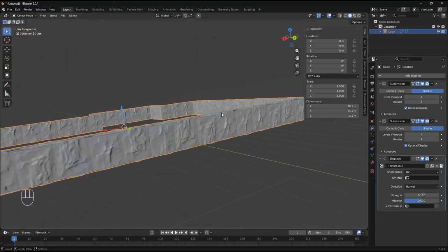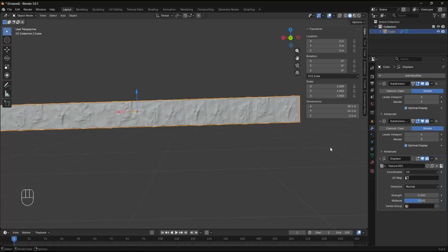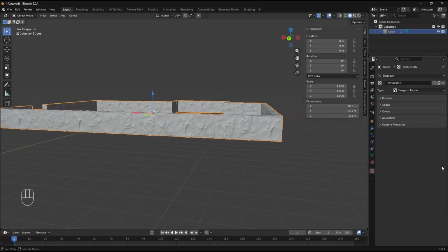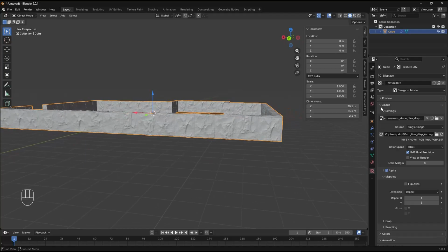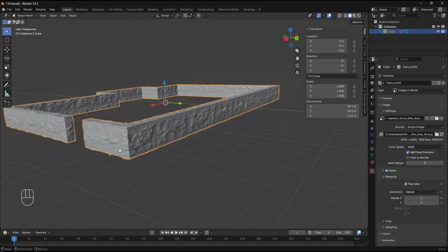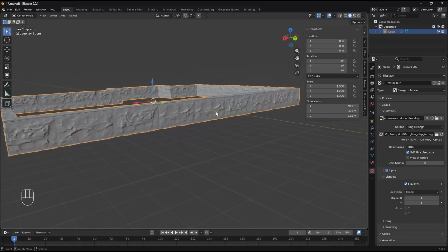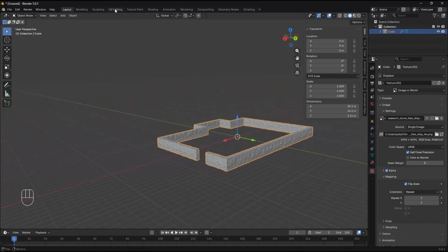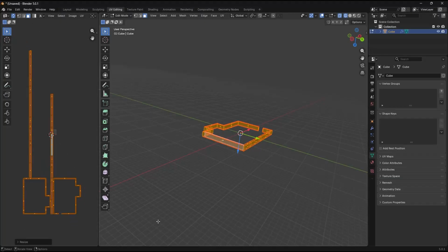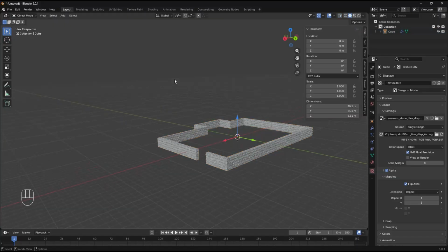And another thing you can also see that's going on here is that the bricks are oriented in the wrong direction. So one way we can correct that is we go to the texture and we go down to the image. You can see under the mapping it has what they call flip axes. And everything is rotated now 90 degrees in the orientation that we want. But the bricks are still too large. So we're going to go back to UV editing, zoom out a bit more, maybe scale them about double what they were. Go back to layout.